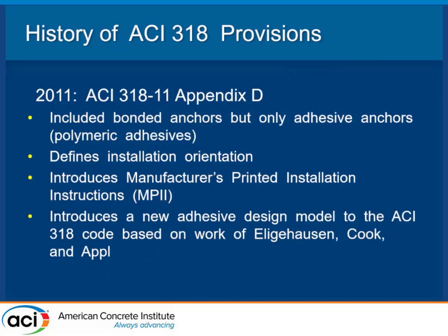That said, we get to 2011, and we had not had anything. We just had mechanical anchors that came into that code. We had not had epoxy anchors, and of course, after 2002, or just around there, is when the Big Dig thing happened, right? That was an adhesive anchor failure, and the National Transportation Safety Board said, hey, you guys need to solve this problem now.